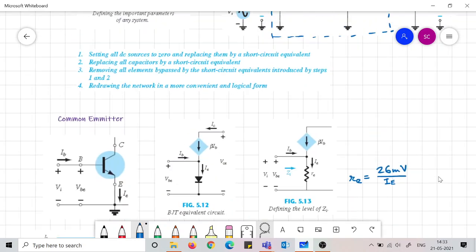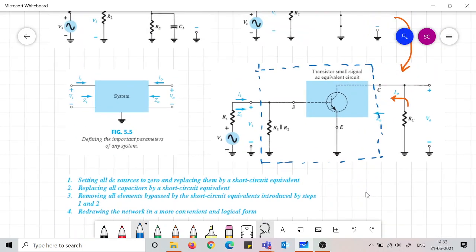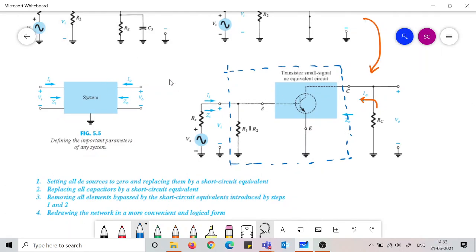So actually, what is the beauty of the two-port system, and why are we not doing a very detailed analysis inside? If for some reason we can know the Zi and Z0 and the gain of the system, then we don't need anything else, because when we give an input here, we can easily understand what would be the output by multiplying with the gain.